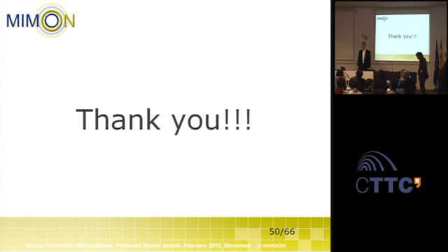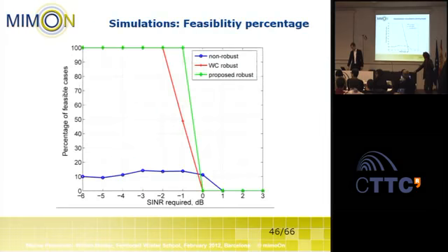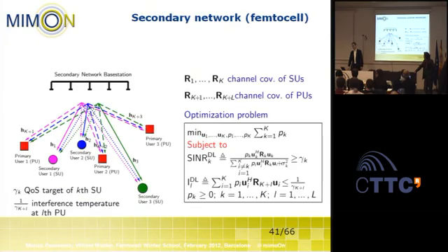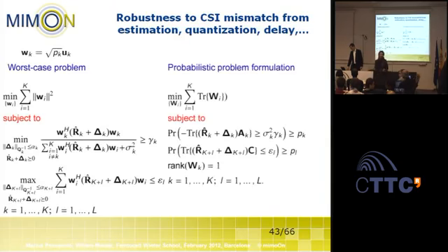My second question was related to this. Initially, non-codebook beamforming was suggested for cell edge users, as you mentioned in your slide, and it was supposedly more successful there because of the long distance. Having a long distance means you will have sufficient angular separation, most of the time. But in a femto cell scenario, having enough angular separation between the primary and secondary user is a kind of far-fetched scenario, and there must be a hardware limitation in terms of beam separation, meaning angular separation between the null and the boresight of a beam. So based on these 4 antennas, or say even 8 antennas, based on your simulation, how much is the minimum beam width or angular separation you can get?